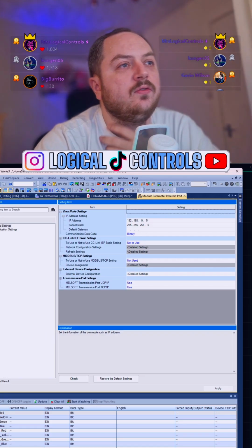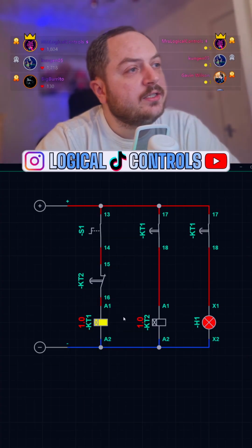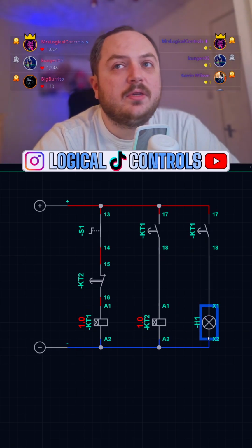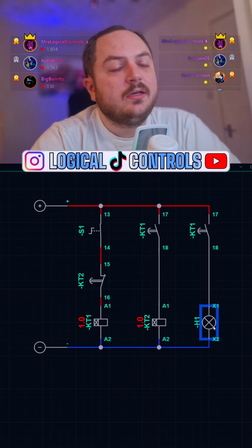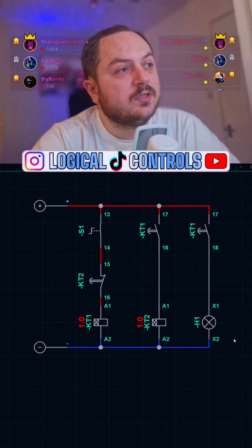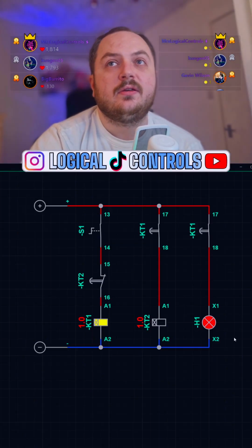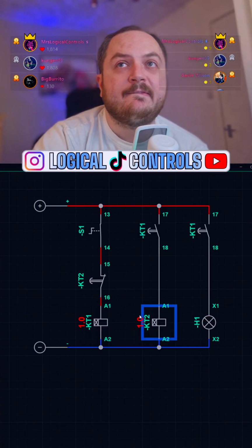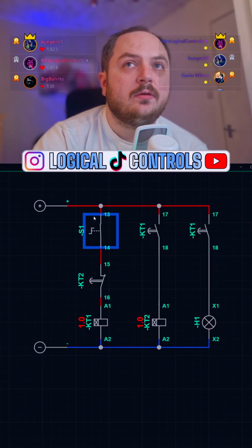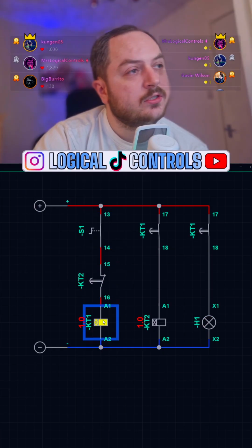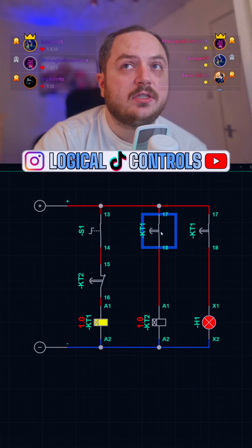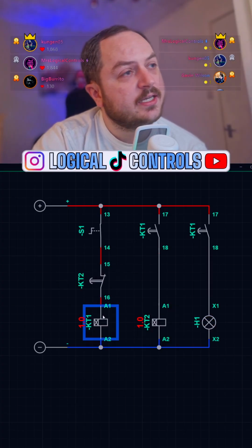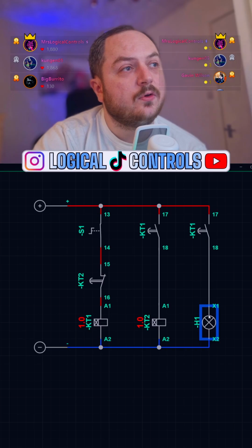Why is it turning off and on by itself? So I just put that together. It's just a flashing light, a flashing circuit basically. You can flash a light, or you can turn a relay on and off with a specific on-off period. There's not a lot to it. You've just got 2 timers. They're both set to 1 second. KT1 is turned on first. When it times out, it closes its contact up here, which then starts to time out KT2, which then resets KT1, and you use KT1 for whatever you're triggering.